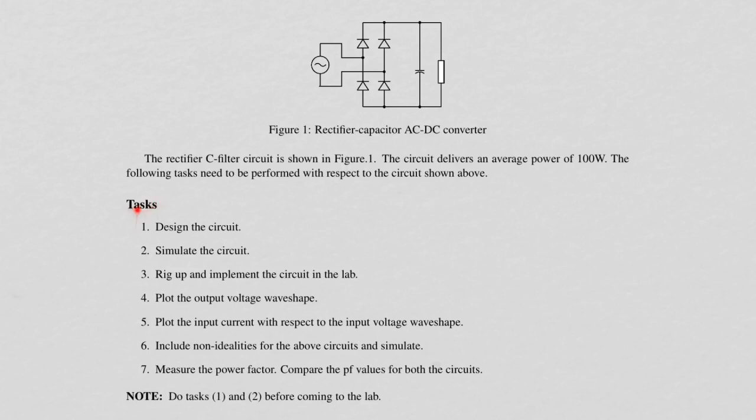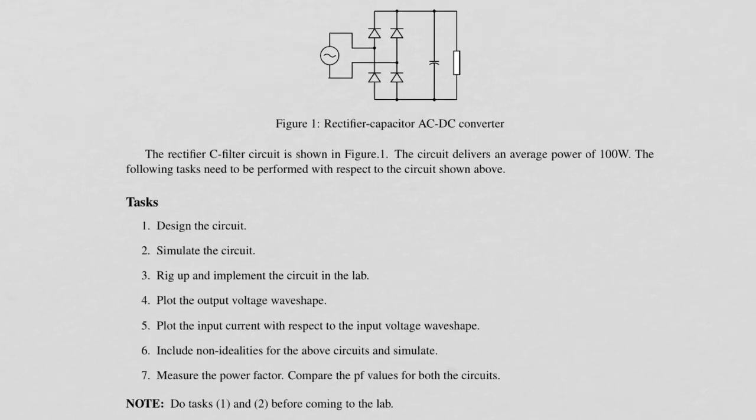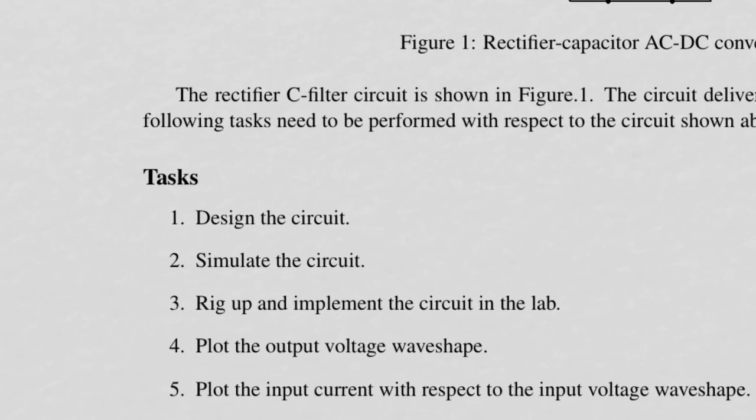Tasks number 1 and 2: design the circuit and simulate. Now this is important. You do it before coming into the lab. So 1 or 2 days before coming into the lab, you will have to spend time on this: design the circuit, get the values of the C and select the diodes, and then use those values to simulate the circuit in ngSpice, PSpice, LTspice, or the MATLAB environment.